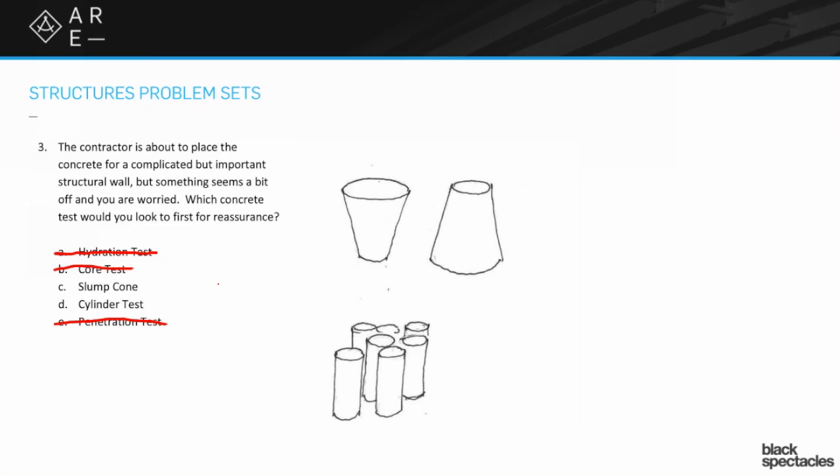Well, that's great, but that's, as Heather says, 28 days later, maybe 7 days later. You might do an early test because you can get a pretty good sense of it, but it's probably way later. So the way the question was worded, it's talking about, I'm worried, I want to find out what's going on. The slump test is definitely a more useful one for you in that context. And I can guarantee you there'll be questions about slump tests and cylinder tests somewhere. I'm not sure how it'll be worded, but there'll be something because it's kind of a key one.